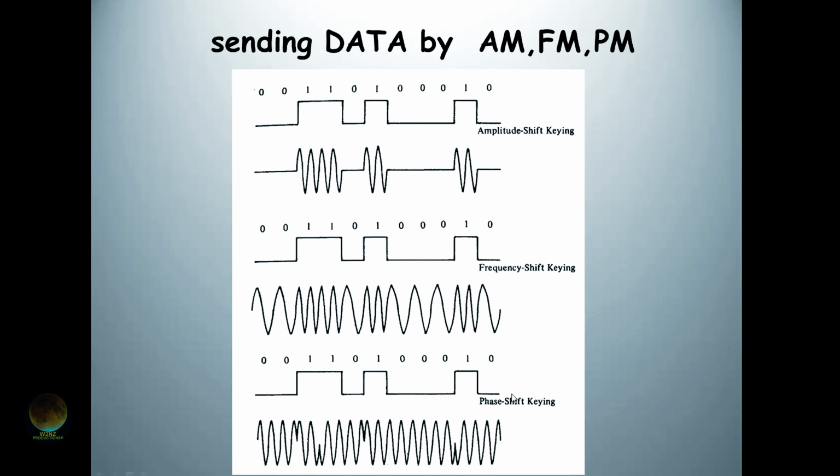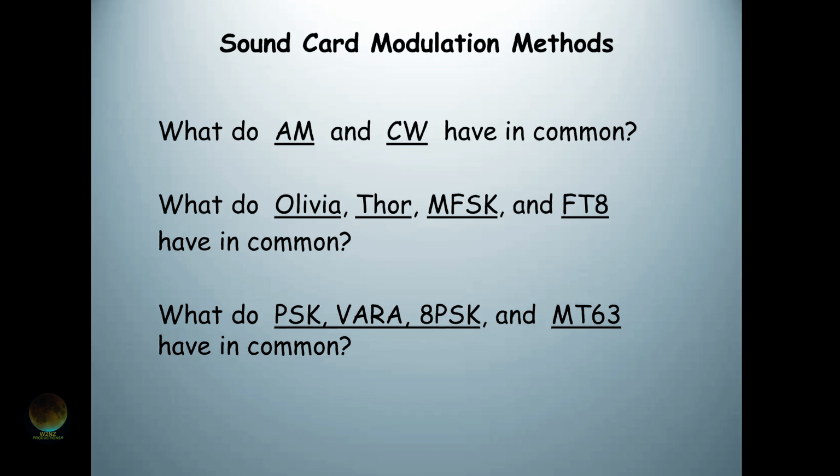Phase shift. This is a little trickier. I had a long discussion about 10 years ago with the author of PSK31. What is phase shift? How do you do it? So the ones might be a phase shift, and the zeros might be no phase shift. But look, how do you show a phase shift on a sine wave here? It's just the timing. So think of phase as the timing. I'm going to come back and show you what that means. It's a little harder to describe it. PSK31 is one of these, and I'll show you how that works.